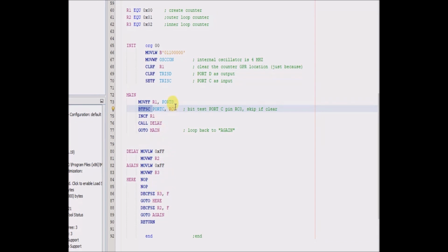and I have it set up with a push button. So in effect what happens is when I push the button, it starts incrementing and outputting on port D. If I remove my finger from the push button, nothing happens. So when I push the push button, it starts counting from 0 to 255 in binary. When I take my finger off, it just stops doing it.